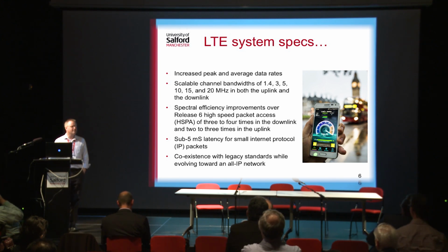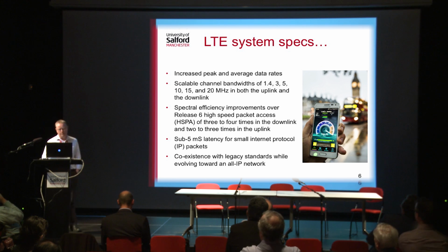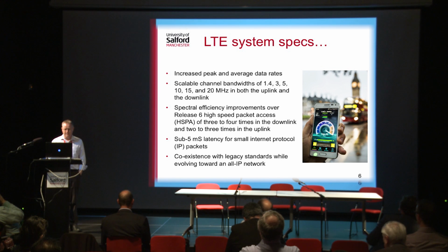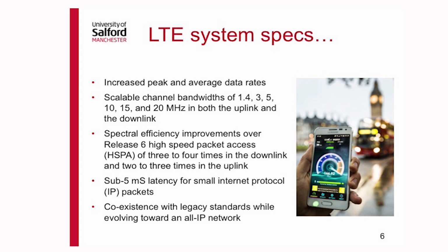We wanted lower latency as well. I talked about things being more interactive before. So the spec for the radio was looking at sub 5 milliseconds latency for small IP packets. Overall system latency, if you do a ping to a server on the internet, is generally between 40 and 60 milliseconds. That's maybe 20 milliseconds less than it is on HSPA, and probably 40 milliseconds less than it is on the original 3G standard, and over half a second faster than it is on GPRS, of course.